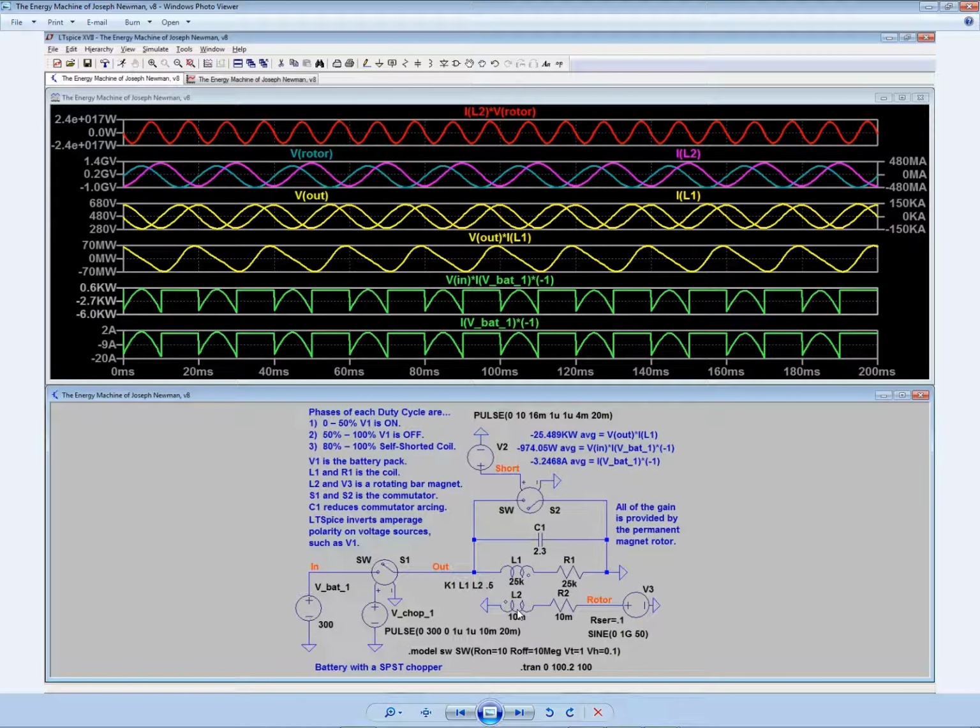Let's see what else. I think that covers everything. So I'm very happy with it, and it's not getting any worse. I'm still making the changes that Constant 314 suggests. He thinks it's odd that in my LTspice, I cannot internalize this resistor as a series resistance on the coil. And if I can't do that, there's no point to internalize the capacitance. Well, I'm not supposed to internalize the capacitance. The capacitance is an exterior set of capacitors.